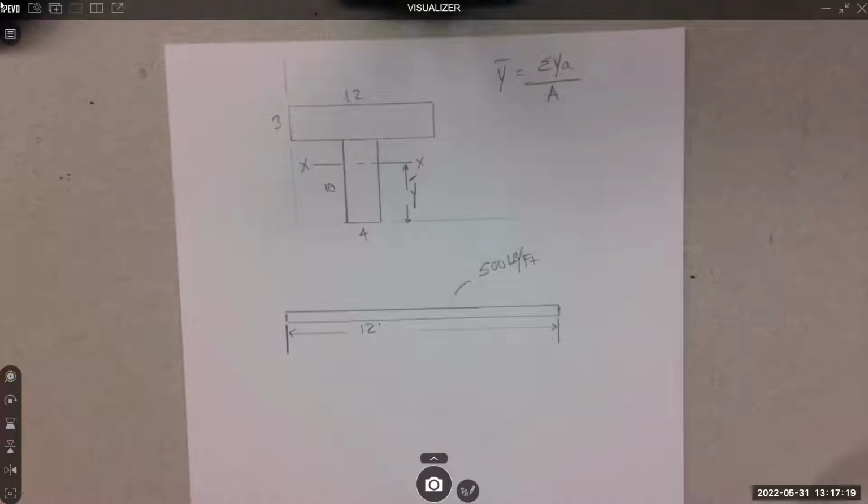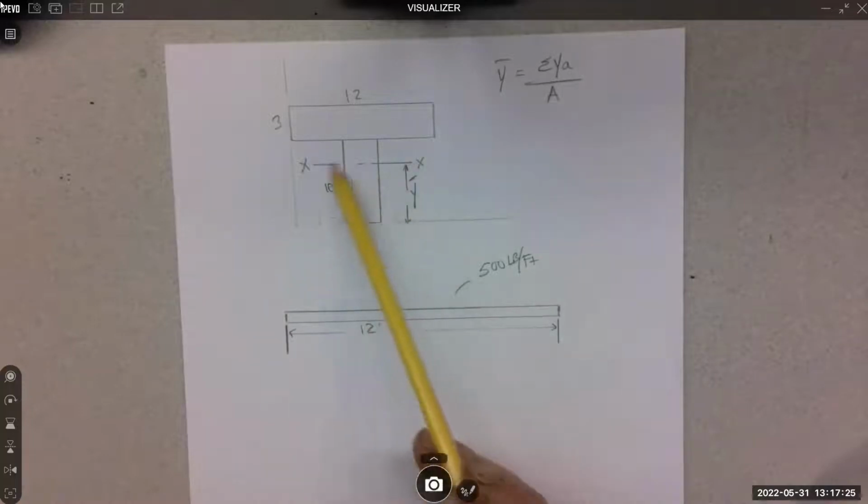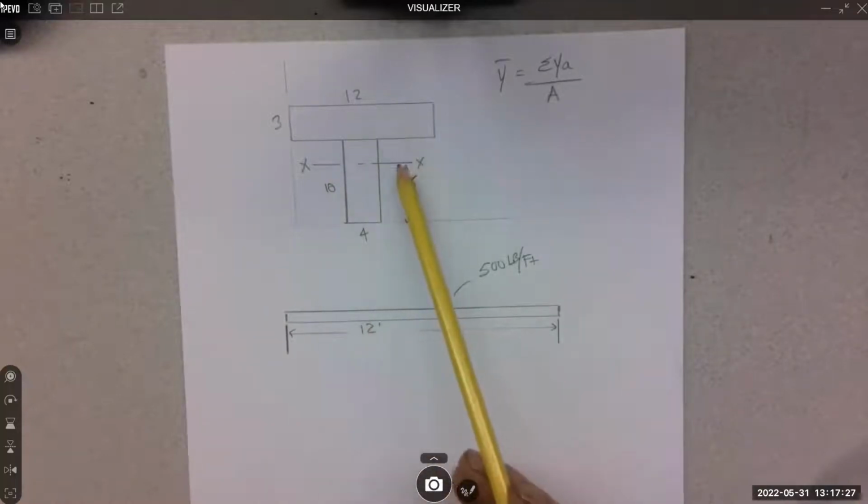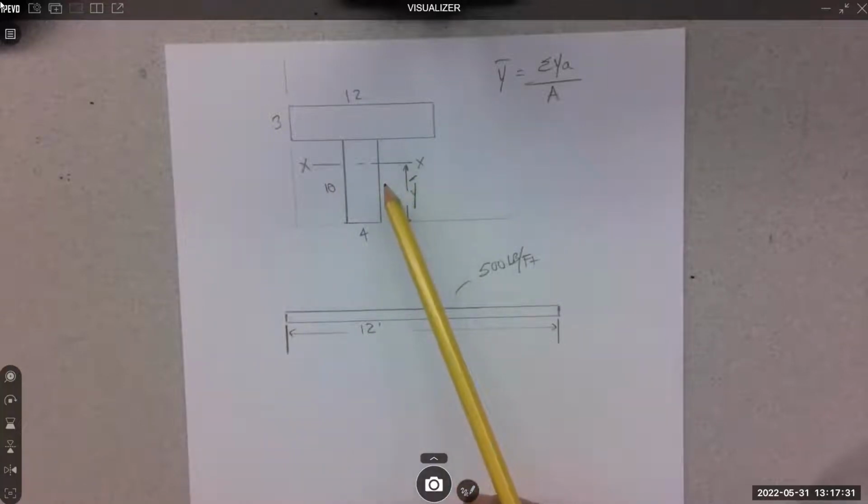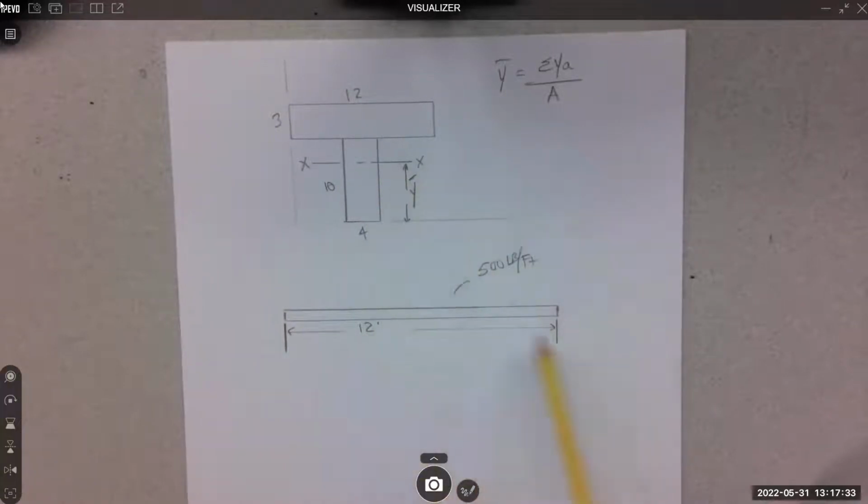But it'll go from the very beginning, statics, through finding where the neutral axis of the shape is, and then finding the inertia of this shape. So we'll have to review that. And then doing the statics, and then doing the shear and moment diagrams, and then calculating a bending stress and a shear stress. So a lot of parts and pieces, but kind of one problem all the way through.